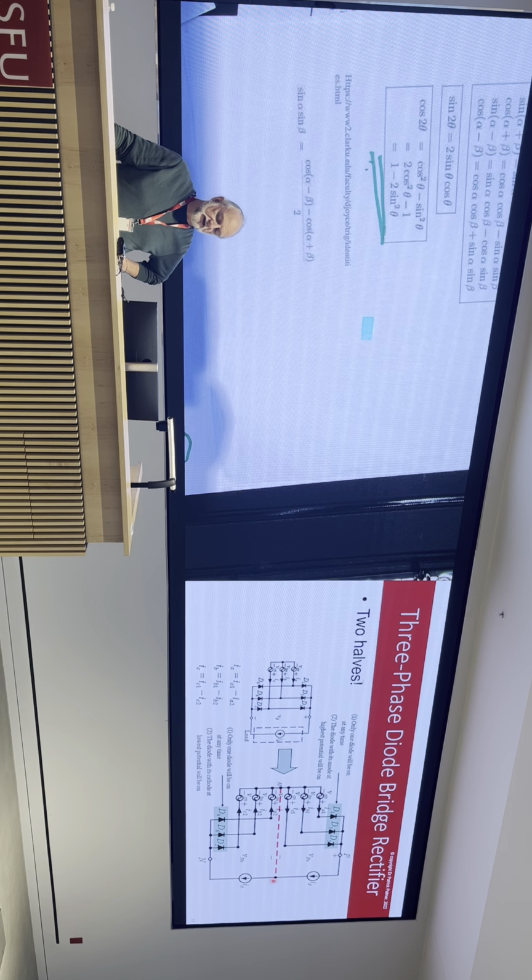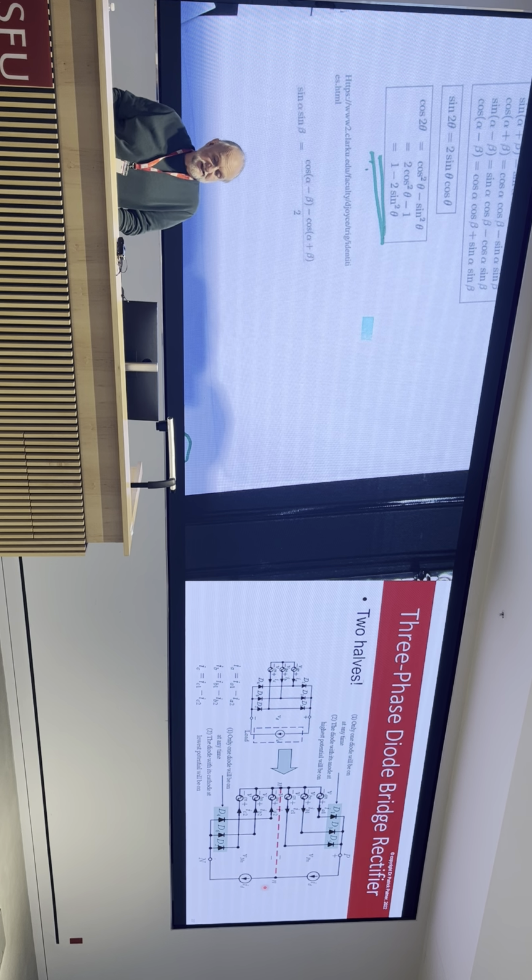I've shown it dotted, but we can say that we've also symmetrically split the load at its halfway point as well. Having done that, we can define this as a point N, and it's all symmetrical, so we've got a point N over here, a point N over there, which is pretty nice. You could say that's neutral. Over here it is neutral, over here it's not really, because it's not actually connected. But we're just exploiting the fact that it's all symmetrical.